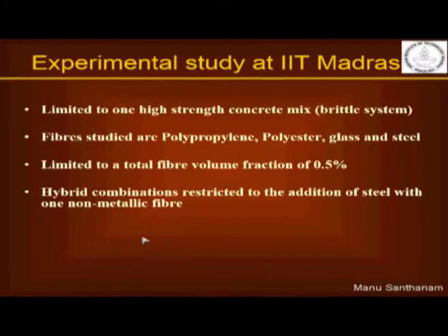On the other hand, at very early stages when the stresses are very low, there is some resistance to cracking that is desired. For example, we know about phenomena such as plastic shrinkage cracking or sometimes thermal cracking, which may appear very early in the concrete's life cycle. We are talking about a few hours to a few days after the concrete pouring. Okay.